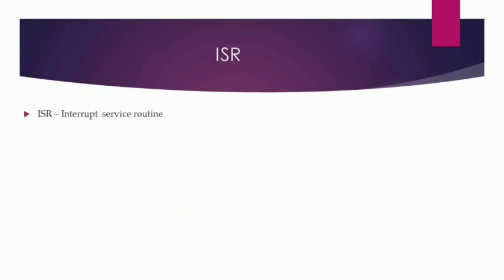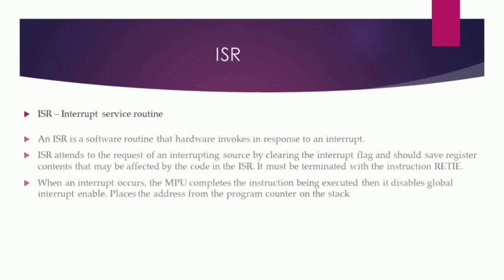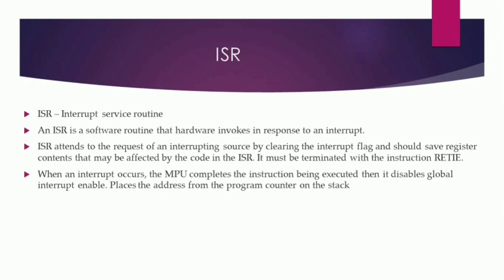ISR is the interrupt service routine. An ISR is a software routine that hardware invokes in response to an interrupt. The ISR attends to the request of an interrupting source by clearing the interrupt flag, and should save the register content that may be affected by the code in the ISR. It must be terminated with the instruction retfie. When an interrupt occurs, the MPU completes the instruction being executed, then it disables the global interrupt enable.